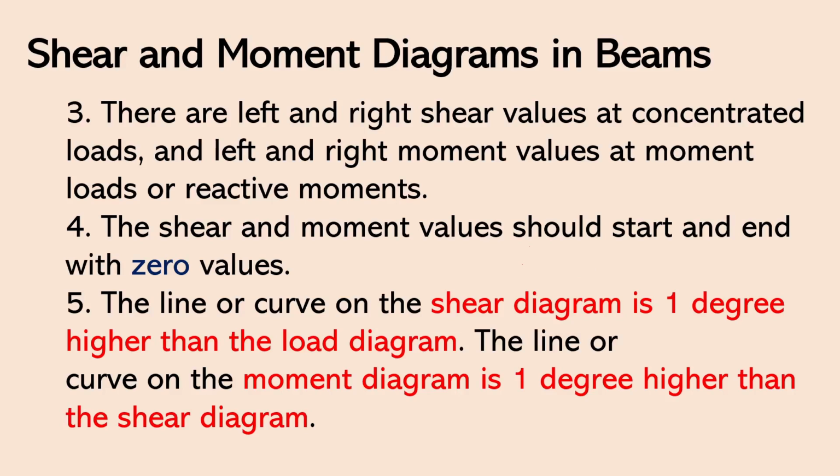And then finally, the line or curve on the shear diagram is 1 degree higher than the load diagram. And then the line or curve on the moment diagram is 1 degree higher than the shear diagram. Now, I will just show you some examples later.